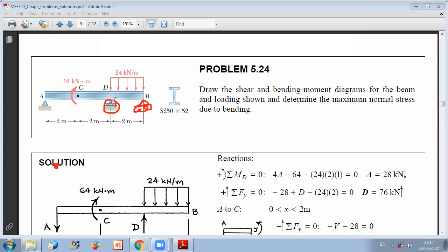Okay, but for a hinge that is connecting two beams, at the hinge the bending moment should be 0. Because at extremities, pin or roller or hinge, the bending moment should be 0. But in case we have an external support in the middle, the bending moment can be different than 0.